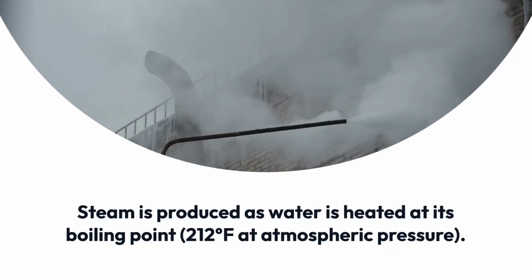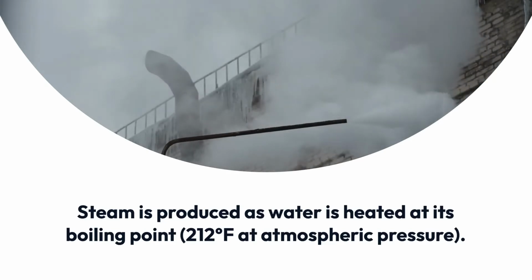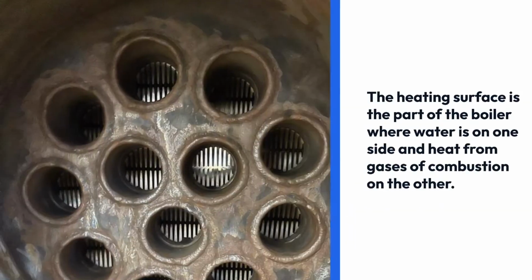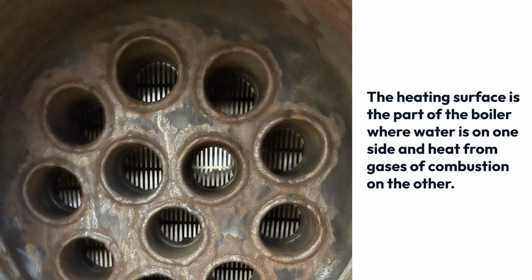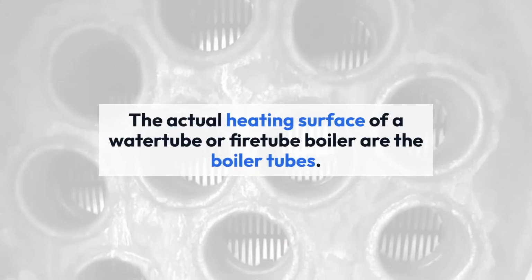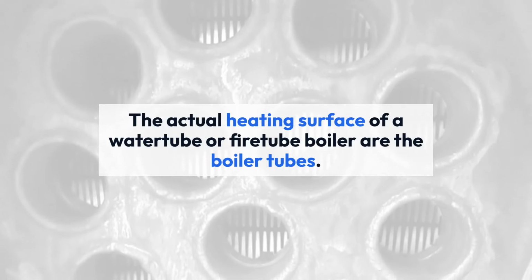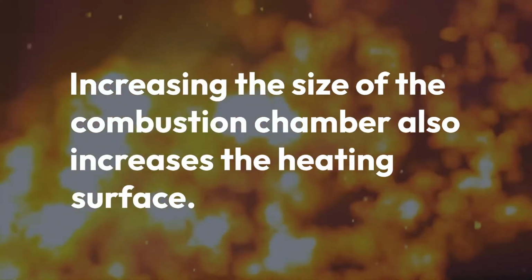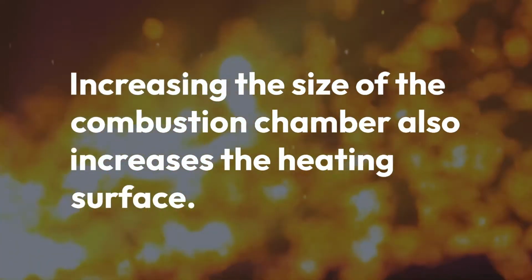Steam is produced as water is heated at its boiling point, 212 degrees at atmospheric pressure. The heating surface is the part of the boiler where water is on one side and heat from the gases of combustion on the other. The actual heating surface of a boiler are the boiler tubes. Increasing the size of the combustion chamber will also increase the heating surface.